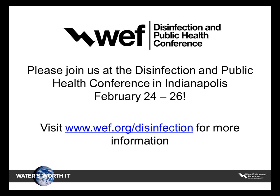I think we're starting to talk almost Title 22 water at that point, aren't you? Sounds like it, huh? Yeah, that's the one that jumps to mind as being as stringent as any of them in California's requirements. I'm trying to remember, it's 2. Somebody help me out on this off the top of my head because we're not California. It's 2 total coliforms. Right. And I can't remember if there's a daily maximum. Gary, are you working in California these days on the reuse side? Yeah, there is a peak. I believe it's 23, Katie.